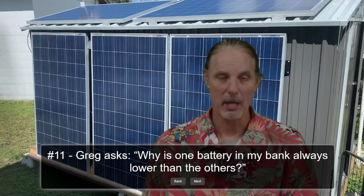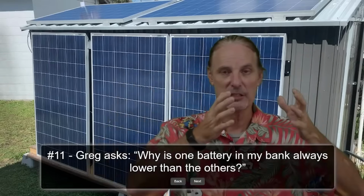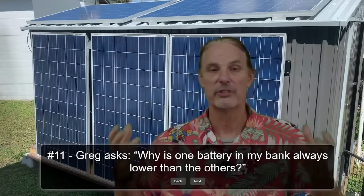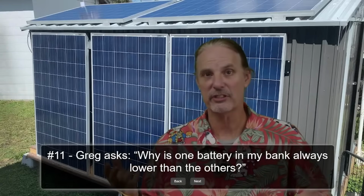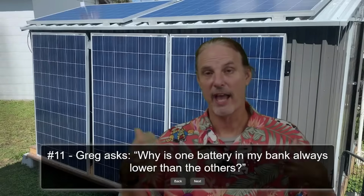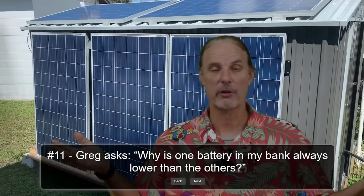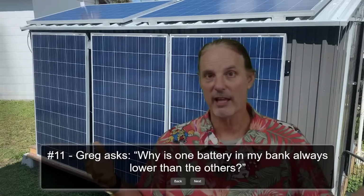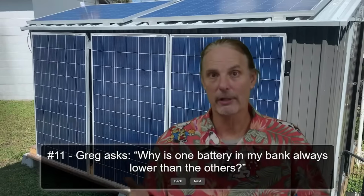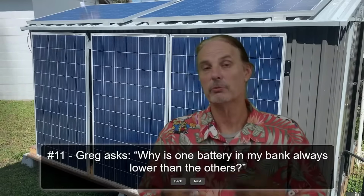And you think of it this way. You put 16 batteries in a bank, and you basically say that the BMS accuracy can measure anything over 16 watts or 15 watts. Well, if you've got 16 batteries and they're all giving 7 or 8 watts apiece, you could still have an output of 100 watts, and not one of the BMSs would even register that anything is going on and the battery is being consumed. If it's set like that at an idle consumption of 60 or 70 watts for days on end, you could literally drain away 10 or 20% of your battery just from idle consumption, and the BMS would have no knowledge of such.